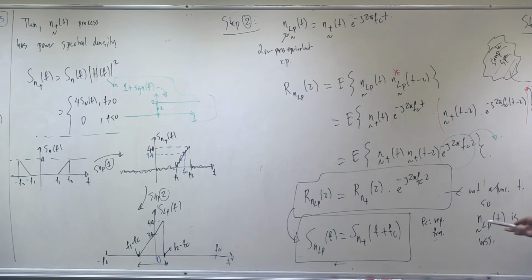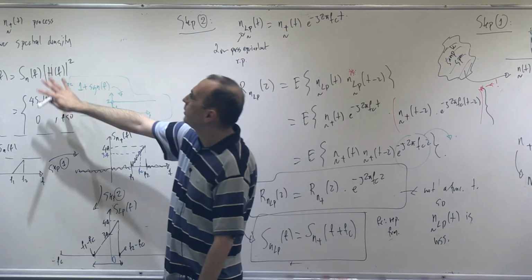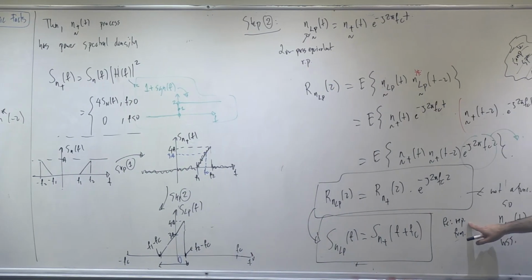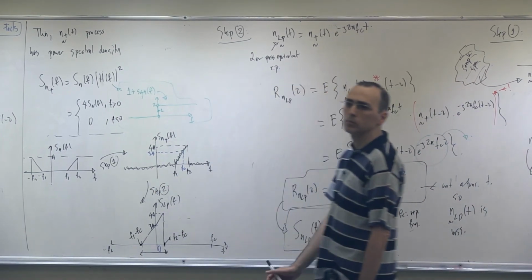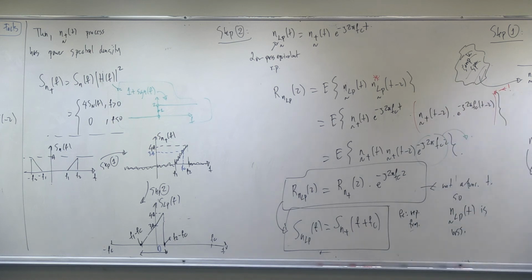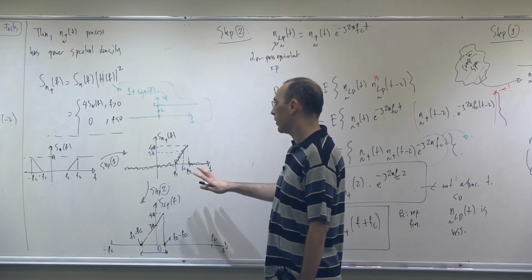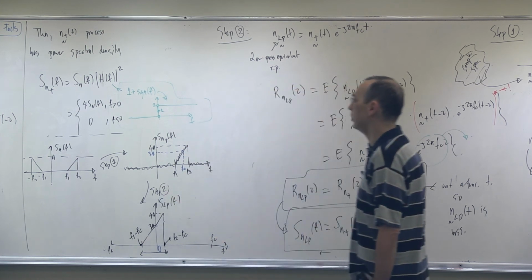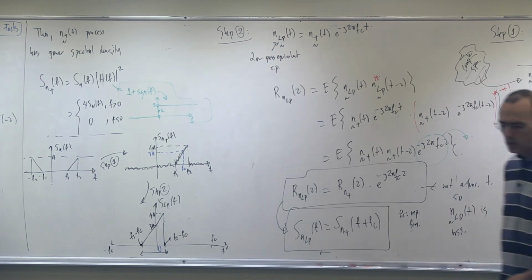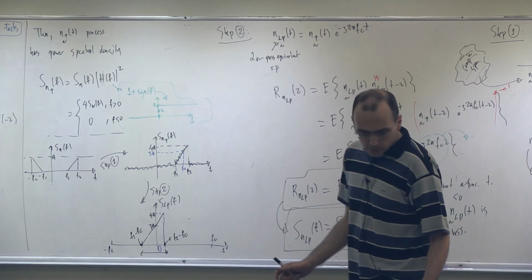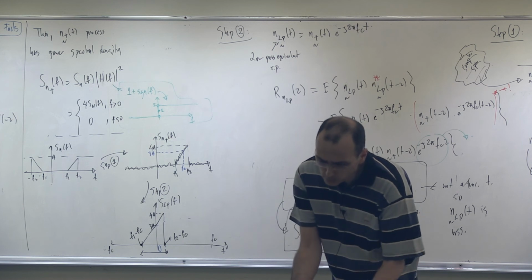So as you see, one important thing one more time about this lowpass equivalence, this Fc has nothing to do with this bandpass signal, bandpass process, etc. I can select Fc at this point. It depends on how much I want to shift to the origin. It's not related to the process. Of course, if this is symmetric and so on, it may have some practical applications. You can select the symmetry center, etc. But I can select this in any way that I want in general. So this is the end of the lowpass equivalent process finding.